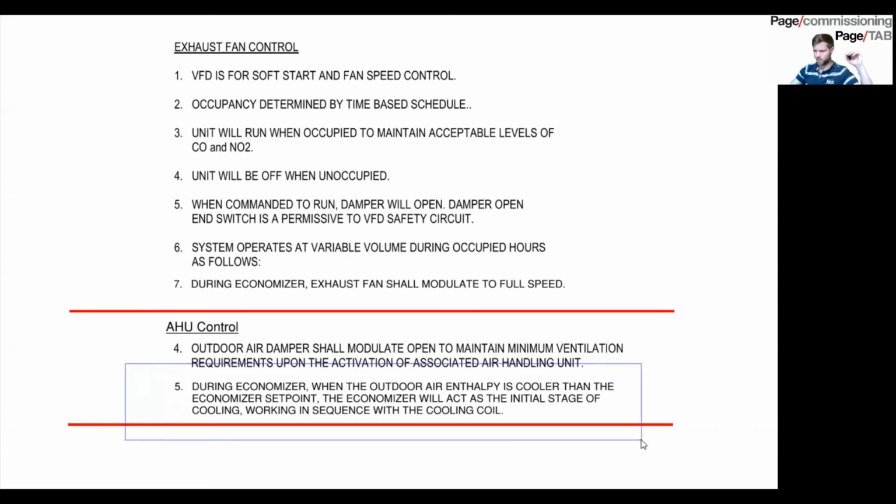So you're potentially mixing 32-degree air in with your return air, which is going to be coming in at 70 degrees. And if you have enough outside air mixed with the 70-degree air, you may be below your typical 55-degree set point. And so at that point, you're just providing minimum outside air, not maximum.